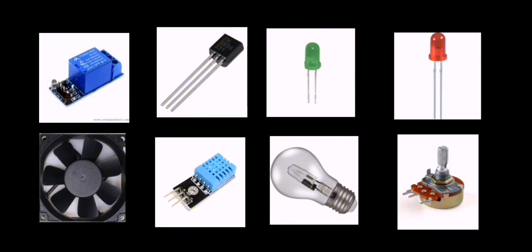The fan is used for cooling when the temperature exceeds the set point. Since the Arduino cannot directly supply the current required by the fan, a transistor is used as a power interface. The transistor's control pin is connected to digital pin 31 on the Arduino. When pin 31 goes high, the transistor conducts and powers the fan. When the pin is low, the transistor blocks the current and the fan stops. The fan is powered by an external source, while its ground is shared with the Arduino ground.